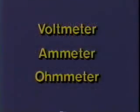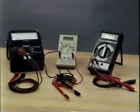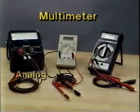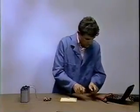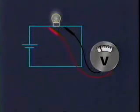To measure these values, we use meters: the voltmeter, the ammeter, and the ohm meter. Today, these three meters are usually combined in one instrument, the multimeter. There are two kinds of multimeters, the analog multimeter and the digital multimeter. When using a multimeter to measure voltage potential, it is connected parallel to the circuit to be tested. This means that it's placed across a device, not in series. The units displayed are volts and millivolts.